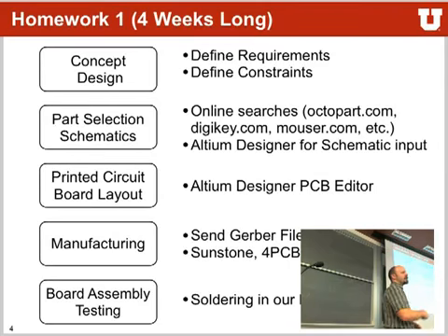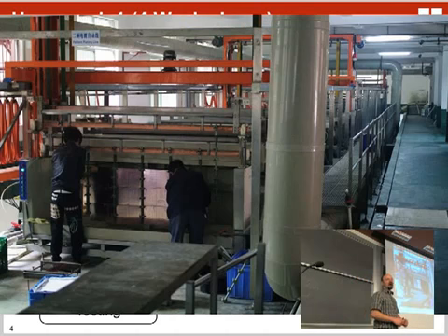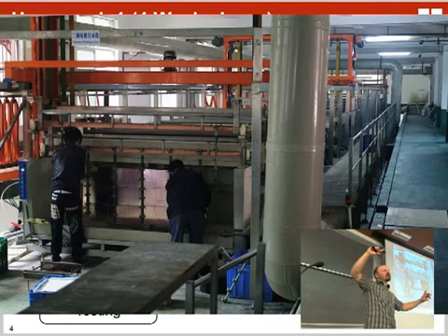Now you have to actually get this thing manufactured. There are lots of steps out there and lots of websites out there that show you how to do that at home with a lot of nasty chemicals, where you put them through a photo processing and then you put them into chemicals to etch the copper away and then out comes your PCB. And of course, there are big fabs that do this stuff for you, right? This is probably a picture from somewhere in China, which you can see the boards here. They are huge panels, about that big, where they manufacture and etch them at once.